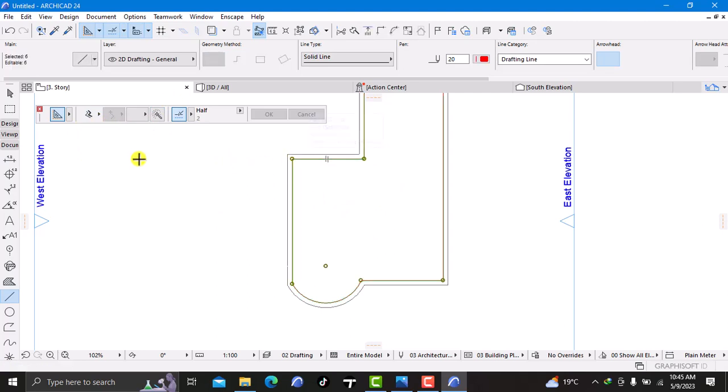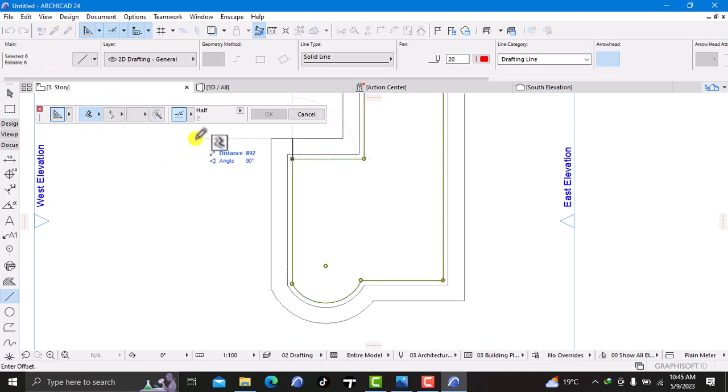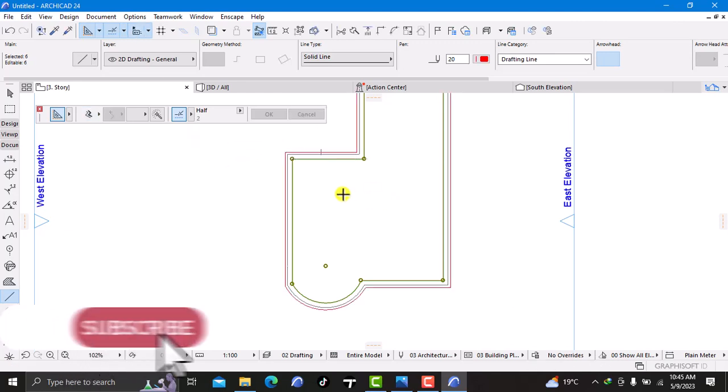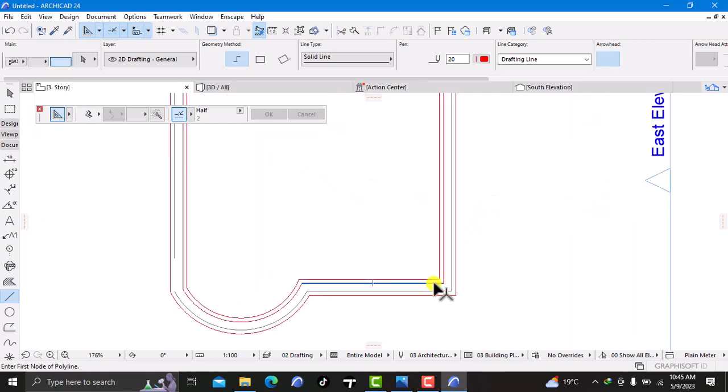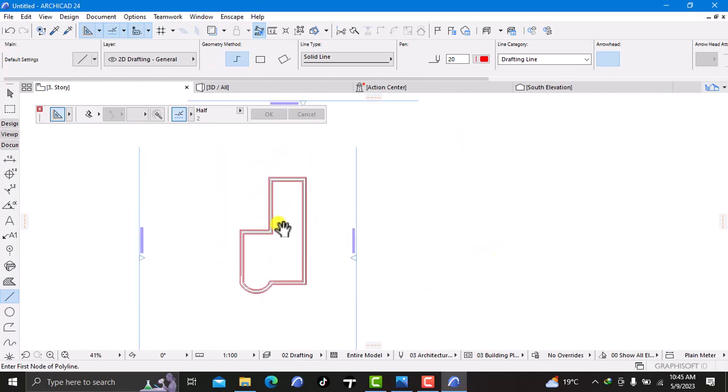Can I just do it again? So the offset tab is on, the magic wand is on. Just basically need to set this distance of 300. Yeah, 300, enter, and then just do a replica of the same. This time I'm just going to set it to an inside distance of 100, then enter, and I can get rid of this one for the center, but I have something of this nature.